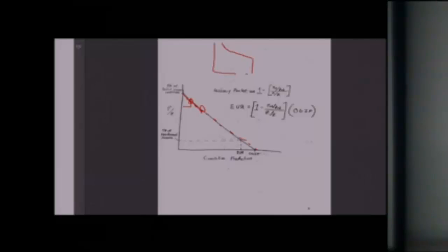So now rate versus time. I'm using lowercase q for rate. And at the same time, if I'm measuring pressure, the pressure may decline a little bit, like this. But what happens here to the pressure? It goes back up. And it usually has a nice little curve like that. So then I may go back on production. Has it reached average reservoir pressure?